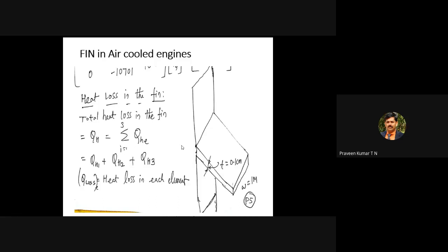Even for conduction, if heat is flowing along the x direction and you increase the area normal to the x direction, then the heat transfer rate will increase, because the heat transfer rate is directly proportional to the area in the case of conduction. In the conduction equation, Q = k A delta T by L. As area increases, the conduction heat transfer increases.